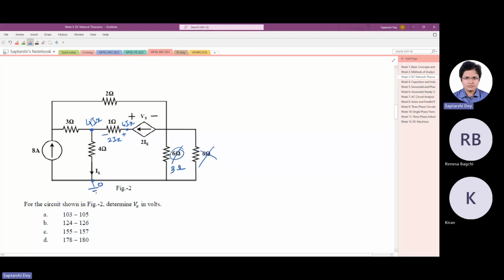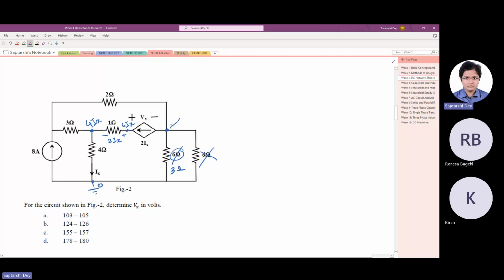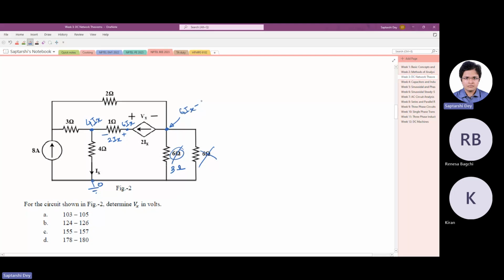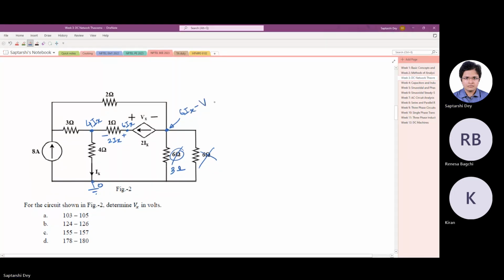All these are voltages, okay? Because I am multiplying the current with a resistance figure, so dimensionally they are voltages. So this was Ix, high voltage 4Ix. 2Ix is flowing through this 1 ohm resistance. So 2Ix rise here, 4 plus 2, 6Ix. And we know that there is a drop of Vx here. So this one is at 6Ix minus Vx.